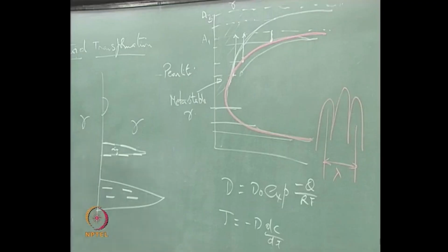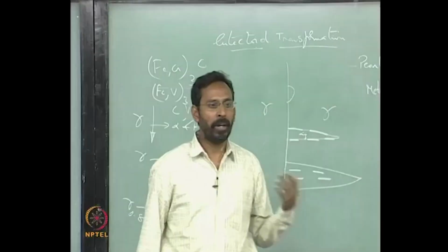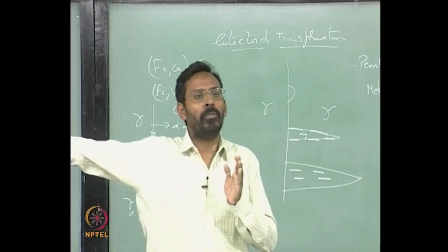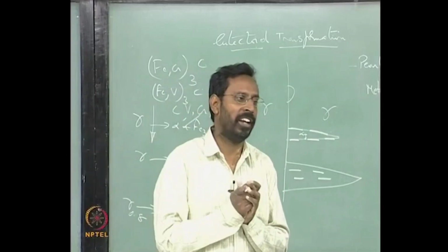and that is what we call a lower bainite, because it does not have time for moving this much distance. So, it is almost like our Al to Cu, theta phase coming out of alpha. So, it cannot go and precipitate at the grain boundaries, it precipitates inside the grain.